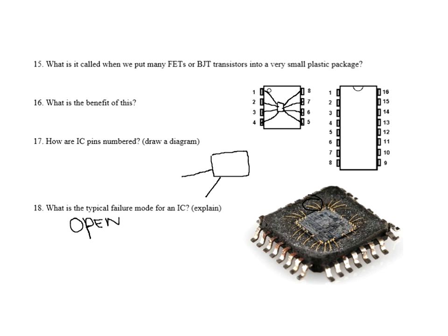Sometimes when that wire burns open, it's so catastrophic, the wire will burn open and flip and lay on top of another wire inside. So even though this wire burned open right here, it moved and flipped over on top of another wire. What does that cause? Well, inside of there, when that fails, it causes a short.